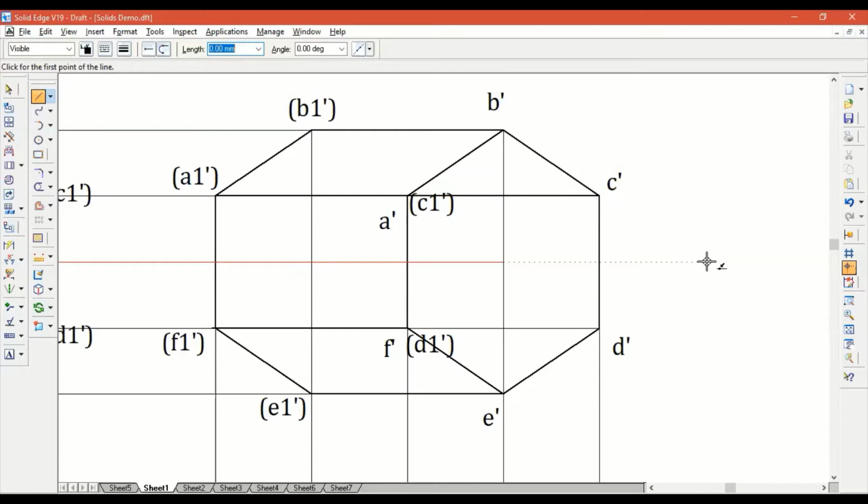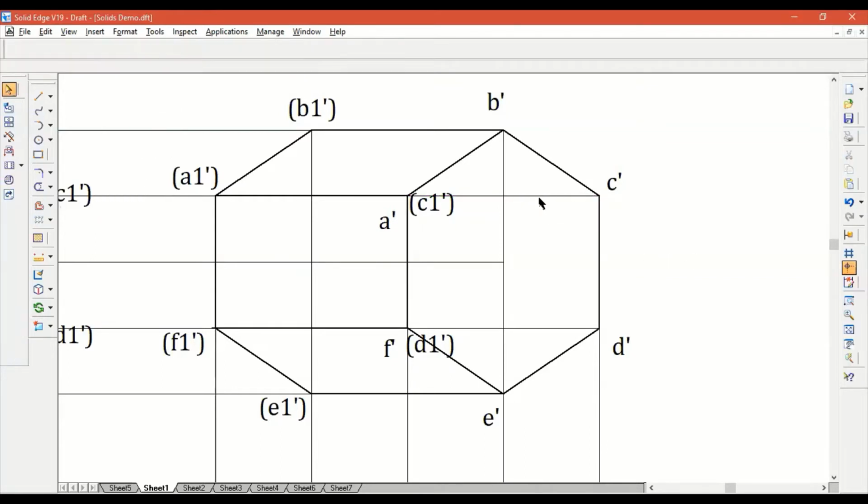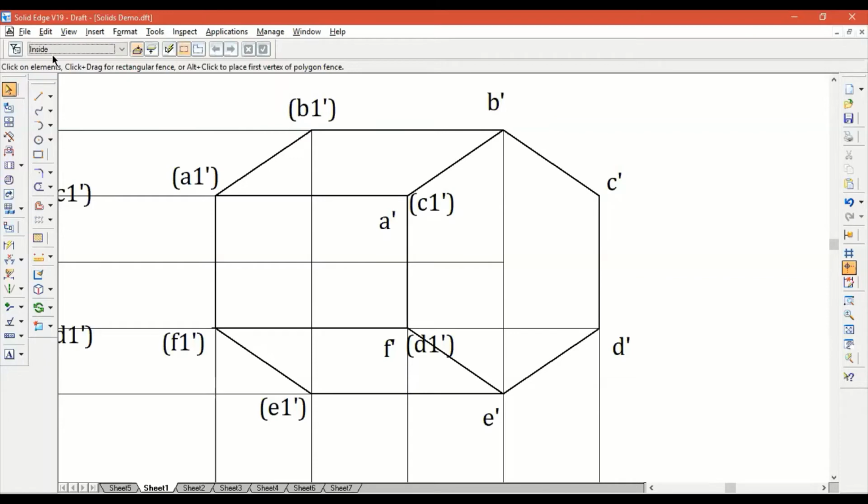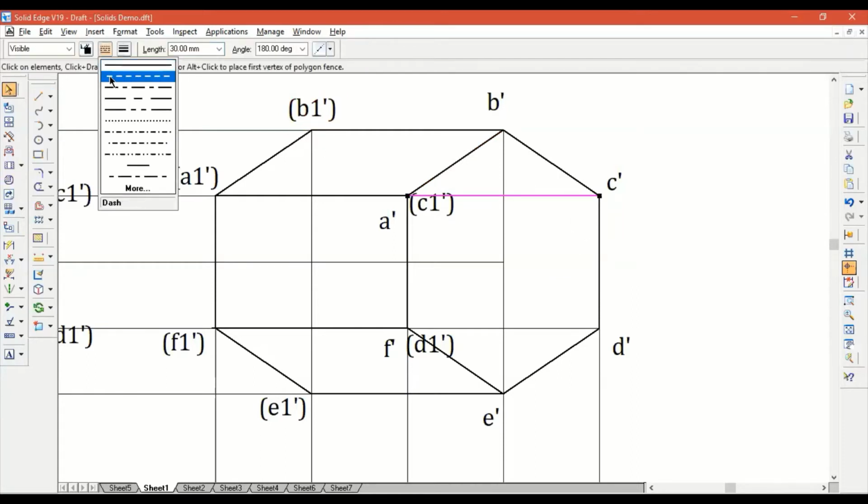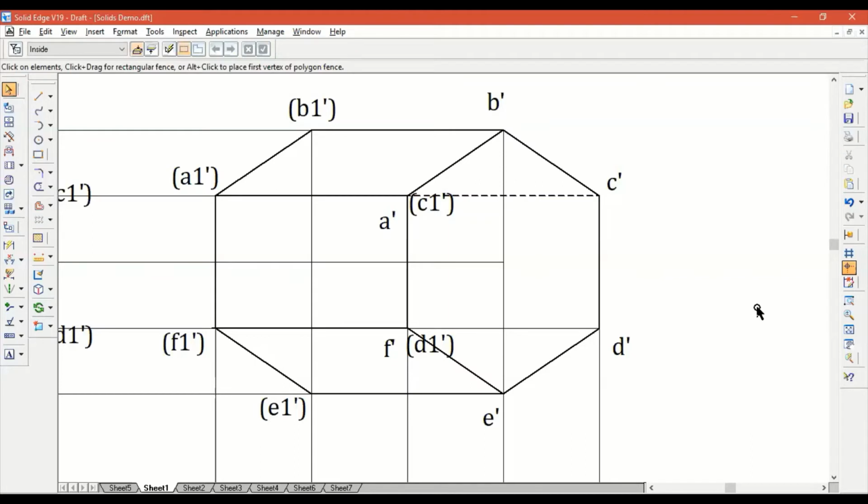Obviously, here you come across an issue because this is a line that goes through the visible base, meaning that this particular line is not going to be visible, which we identify as a discontinuous line like that. So I'm just deleting the previous projection line and marking it as a discontinuous line like that. Remember, there are a few cases in which a real line is going to be identified as a discontinuous line because it is invisible.